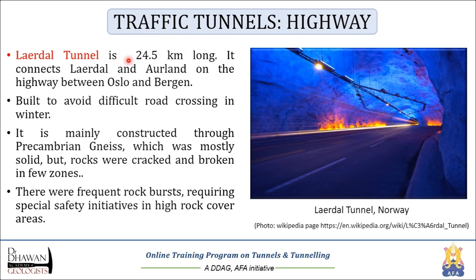Example is from Norway. Here the Lærdal tunnel, which is 24.5 km long, connects Lærdal and Årland on the highway between Oslo and Bergen. It was built to avoid road crossings in winter. It is mainly constructed through Precambrian gneisses, which was mostly solid, but rocks were cracked and broken in few zones. There were frequent rock bursts requiring special safety initiatives in the high cover areas during construction of this tunnel.